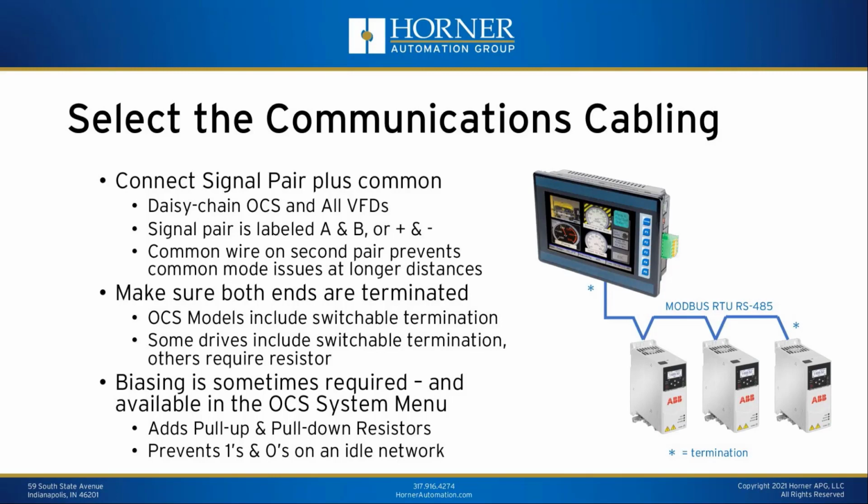From an Ethernet standpoint, if you were to choose one of those networks, you're talking about traditional Ethernet type communications cabling where you wire from each component back to a switch. You're all pretty much familiar with that. From a CANopen standpoint, CANopen is typically a daisy chain using special CAN cabling, but I won't cover that in a lot of detail. What I am going to cover, because of the commonality of it, is the RS-485 wiring over Modbus.